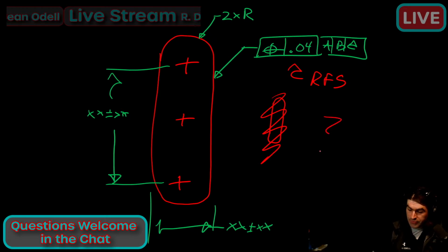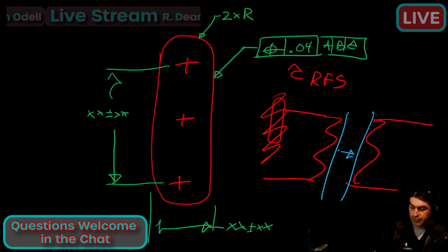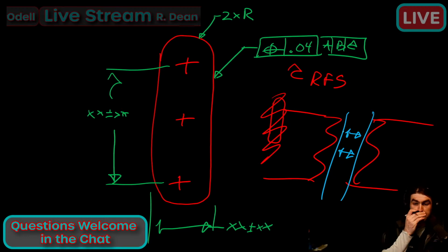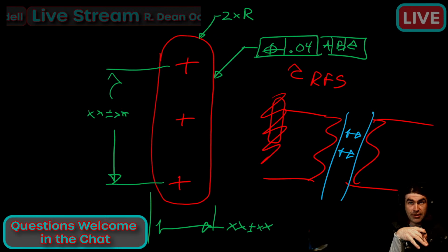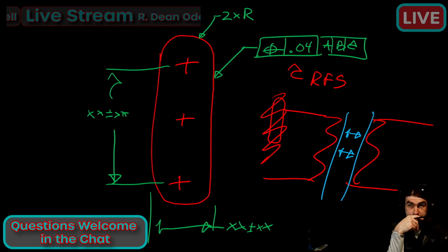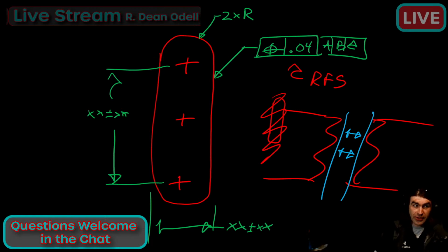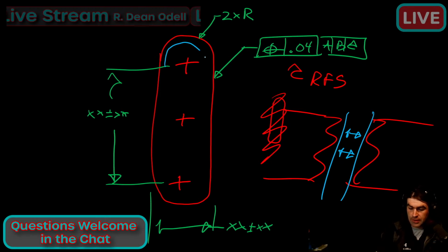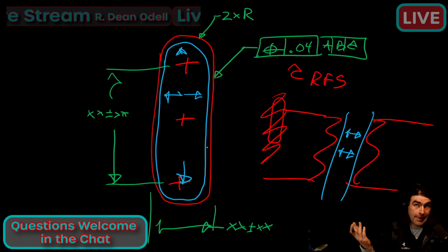When we're measuring a hole, the definition is pretty straightforward: the unrelated actual mating envelope. It's the largest similar feature you can fit in there, so you imagine the largest gauge pin you can fit. For an external cylinder, it's the smallest cylinder that collapses on it. Now you could say, okay, all you've got to do is get a slot-shaped unrelated actual mating envelope and expand it simultaneously in all directions. I guess. I don't know.